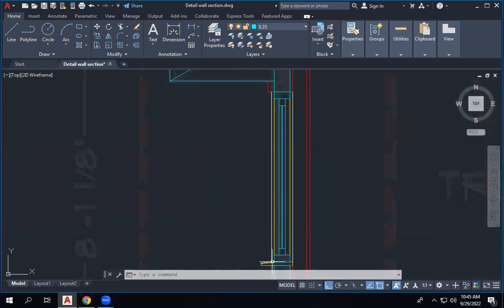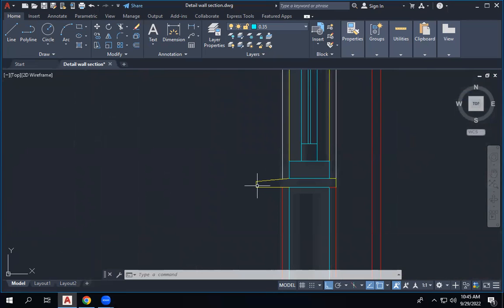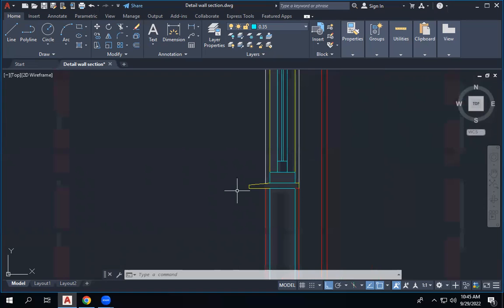So I guess we would need to look up a window that has that to know what to write about it? Yeah, you just put, it could be a concrete ledge. Okay. You can say it like that, concrete ledge. But give the dimension that you have given here, because that's important. The contractor needs to know how far extended you want this concrete to be. Mostly these details will be done by architects, but I'm doing it now for the wall sections, because you might be doing the wall sections internally, not the external ones, because you are in the interior design section. But you need to know what is happening, otherwise when you get a drawing you don't know what is there, and at least to differentiate. Right.